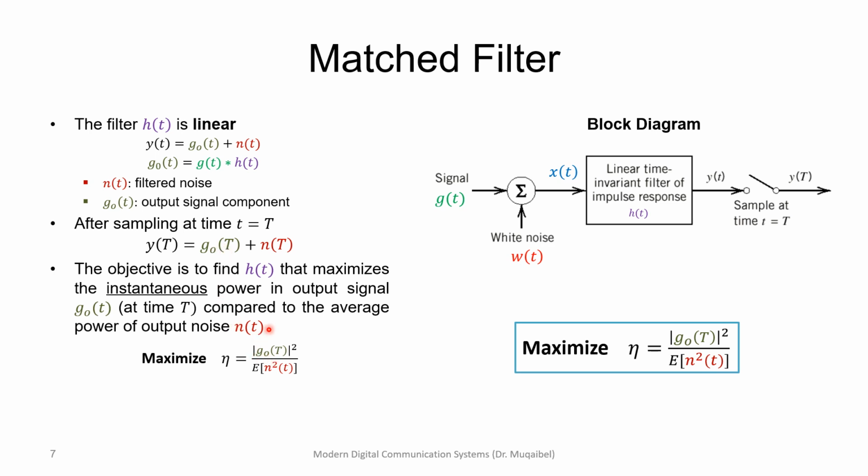Because we're looking at power, I'll look at that square, because it's a constant or single value, I'll just square it. And also for the noise, the output noise is nothing but the expected value of N naught squared. And of course, we look at the expectation of this value because it changes with time. Now that's your original signal. That's not random, and that's random here, and this is why we have expectation.